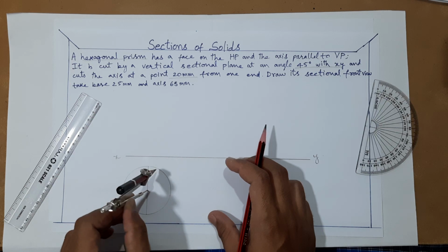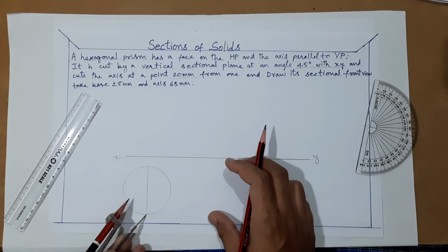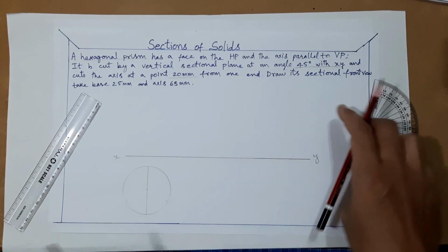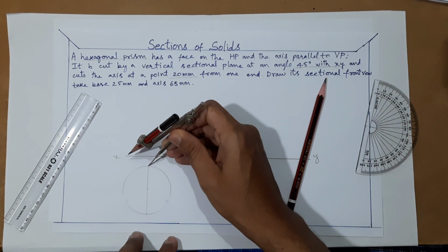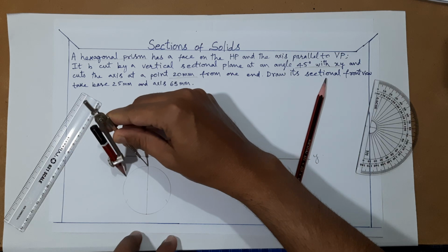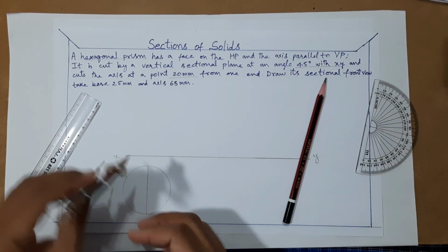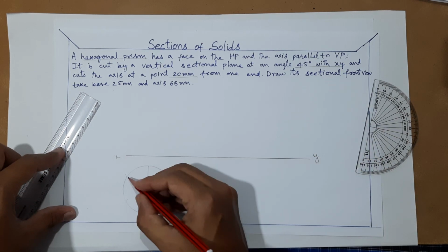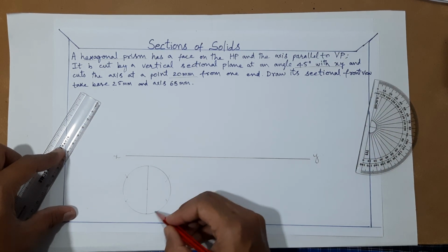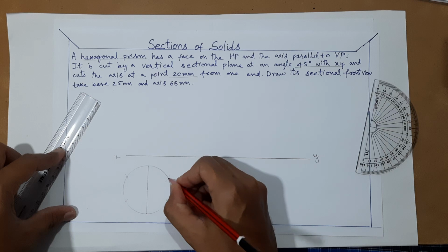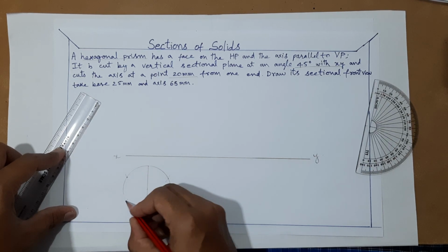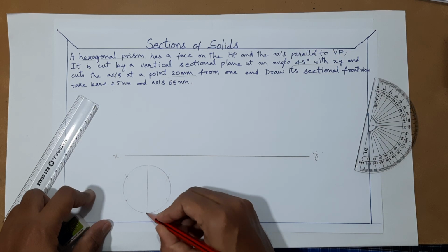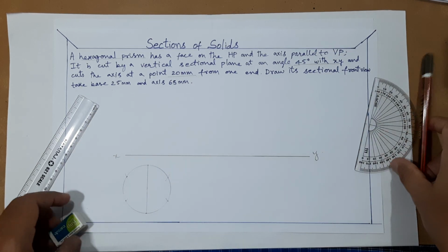See, this is 25 radius only. Take this one as center, draw one arc here, another arc here, and take this as center, draw one arc here, another arc here. So we will be getting some points over here. Then these 2 points are anyhow available from the diameter line.